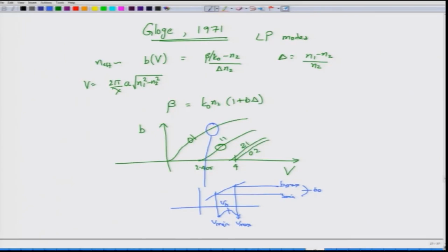So, it is not a linear relationship, and because of this being nonlinear, the propagation constants actually depend on what lambda you are transmitting or on what pulse width you are transmitting, and most importantly these parameters are further functions of V, and the derivatives of these are what is going to give you the dispersion in the fiber.